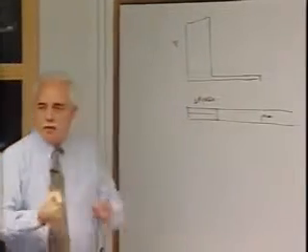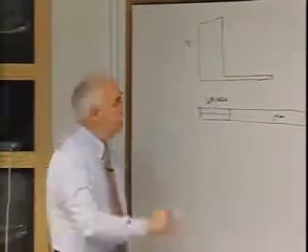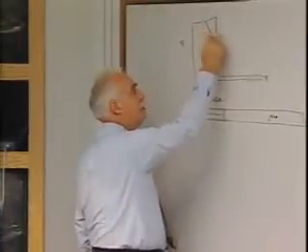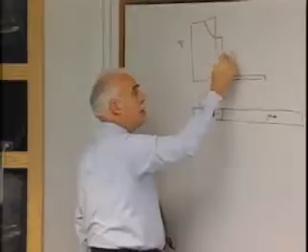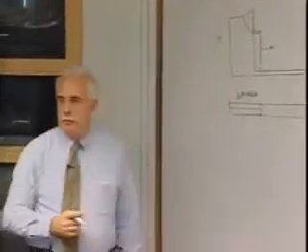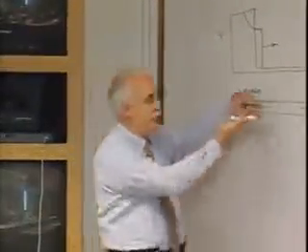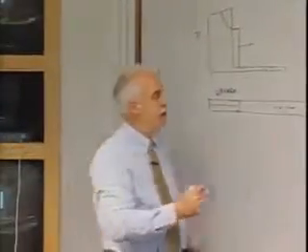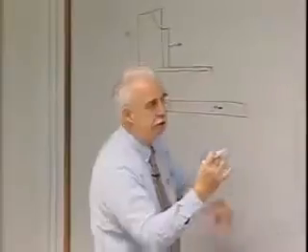The diaphragm can't take that pressure. The diaphragm blasts, and you get an expansion wave coming back here, and a shock wave traveling in that direction. Okay. The reason we had to go to 2 feet is you get a boundary layer building up, and if you want some test gas, you basically, I've kind of got this reversed here.